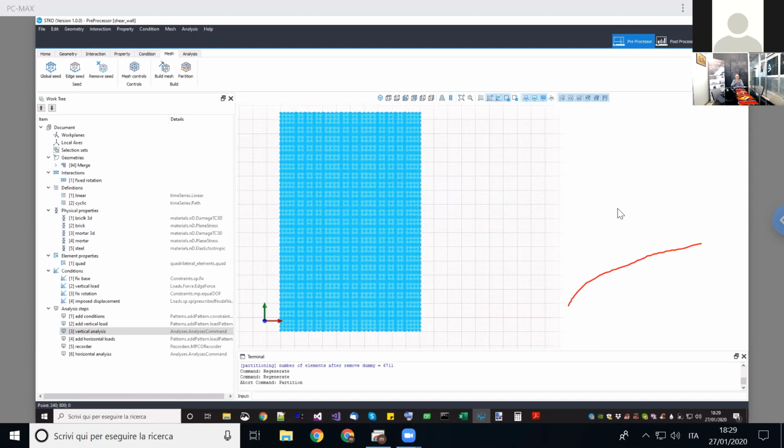And probably the last one will be on how to use micromodeling to predict the material properties for equivalent continuum models, what Professor Derisi was saying before. Because now we have the continuum isotropic model, the orthotropic adapter, and then we have a procedure to use a representative volume element and to get from these representative volume elements all the equivalent strengths in the different directions. So this one will be the last topic that we're going to cover in this series of webinars.